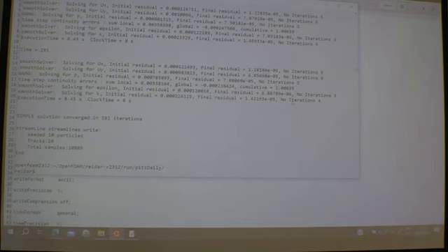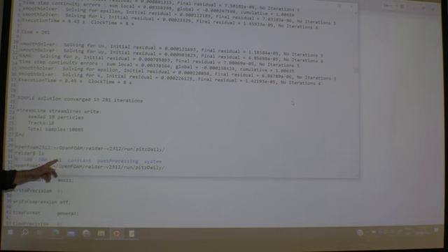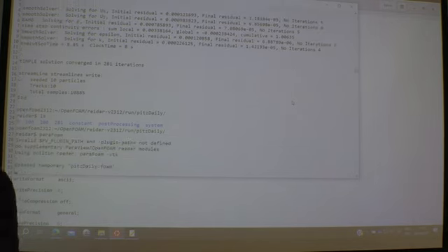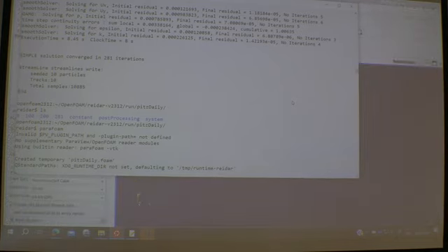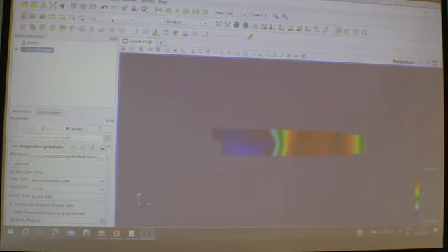What have we received? Yeah, you have a couple of time folders here, time result folders, but it's only the last one that is of interest. I mean, you don't have a real development here that's physically correct. It's a steady state thing. So now, paraFoam, just to have a look. Apply, and then here we have, say, the velocity, and we can play it to the end. There you have the steady state.